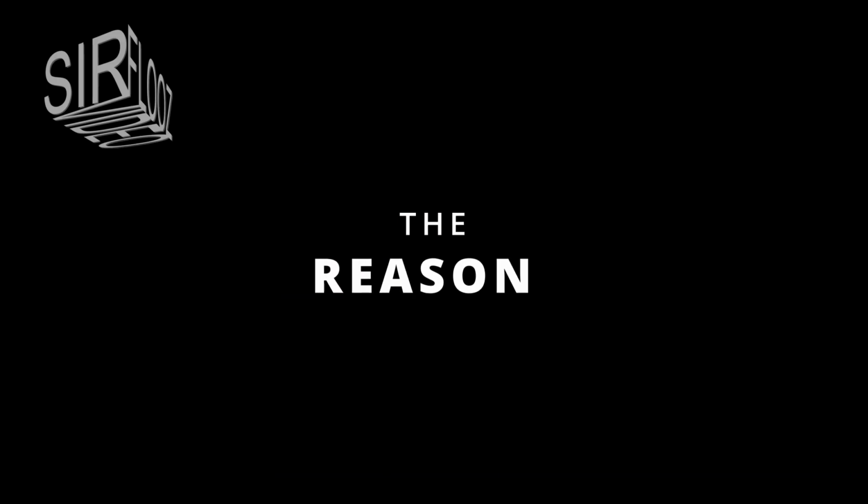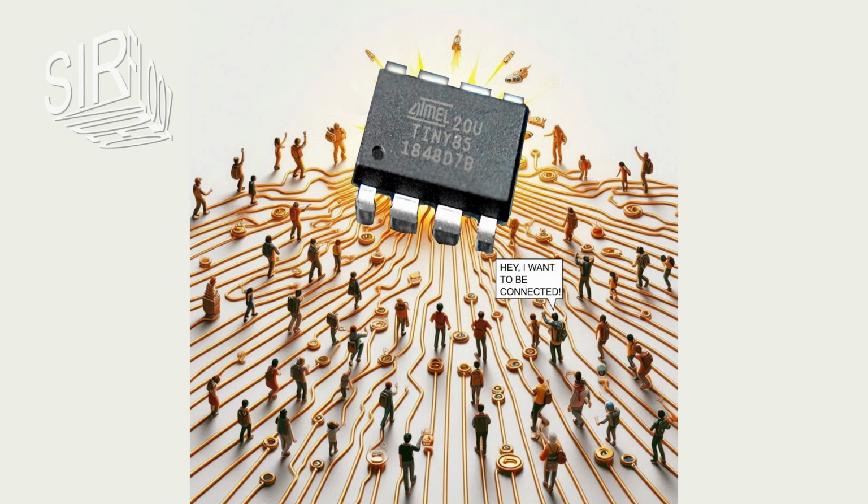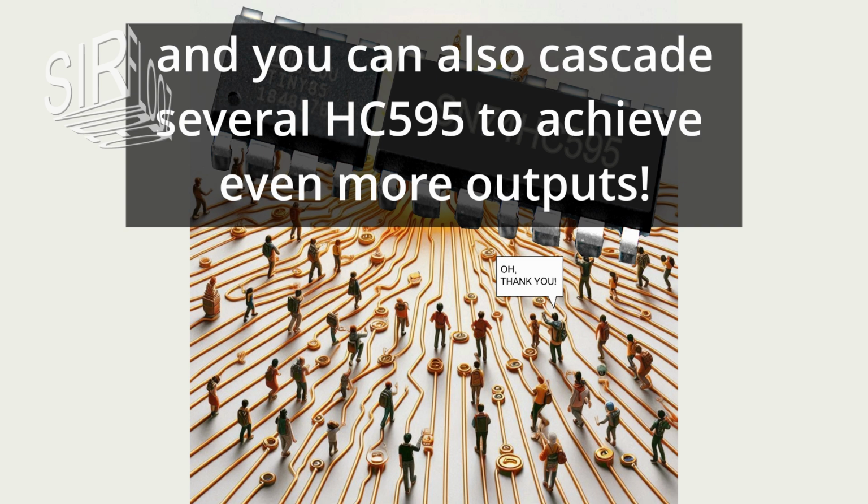What is the purpose of a shift register? Every microcontroller, or MCU, has a specific number of output pins. Especially low-priced chips like the ATtiny85 and PIC16F often have only a few output pins. Often this is not enough. With the HC595 it is possible to expand the output pins by another 8 pins.